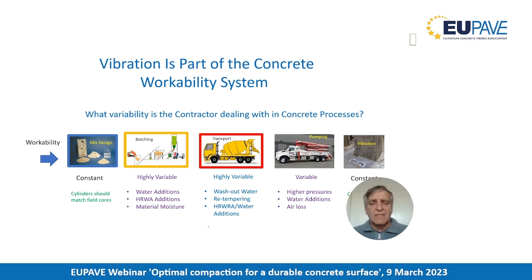In this instance, unless we're looking at bridge decking, it won't be pumped, but there is some slump loss between the target and what happened in transit to what got delivered to the paving machine, and even how far away from being run over by the paving machine the concrete was sitting.